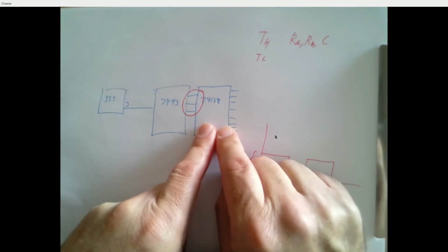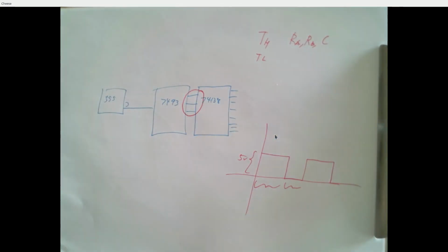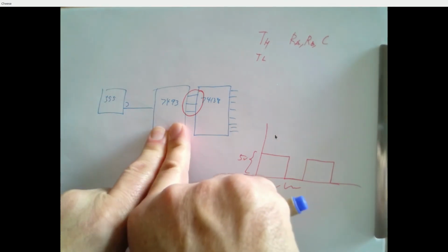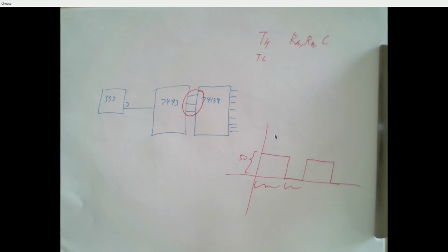Same thing with the decoder. We could write a truth table, 3 to 8, big long truth table, 8 rows, 8 outputs, write the equations, minimize, and so on. But we don't do that. We have this in our parts box. We have this in our parts box. And this is a mindset we're shifting into very quickly now at this part of the course. We're going to start developing circuits based on circuits we've already developed.